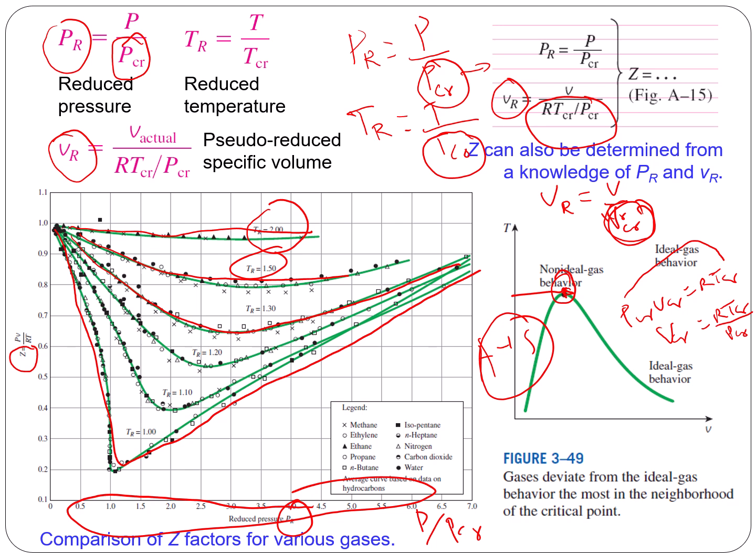If the pressure and temperature are given, let's say we find the reduced pressure is 3, and the reduced temperature is 1.5, then you just do like this. So this is where it is, 1.5, and corresponding to this, you can find the value of Z. So this is how you can use it if the pressure and temperature are given. Once you know Z, then you can use the modified ideal gas equation to find the unknown. Okay, so that's how we do it.